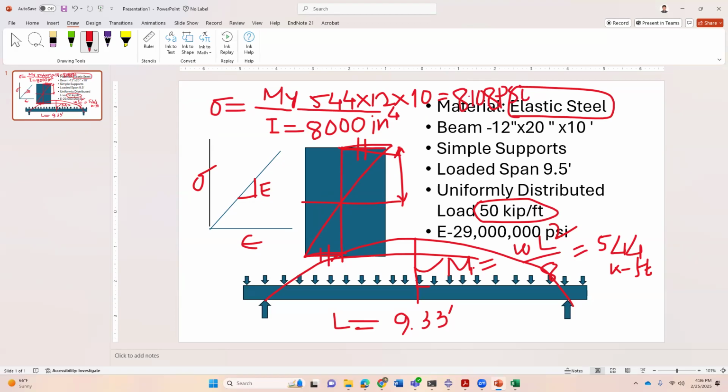So that's the flexural stress we calculate from the flexure theory, right? For a simple, what's called the isotropic beam, or linear elastic beam, basically. As long as there is no plasticity, this formula is valid. So we did not introduce any material nonlinearity, material plasticity in the model. So we should get that value as the flexural stress.